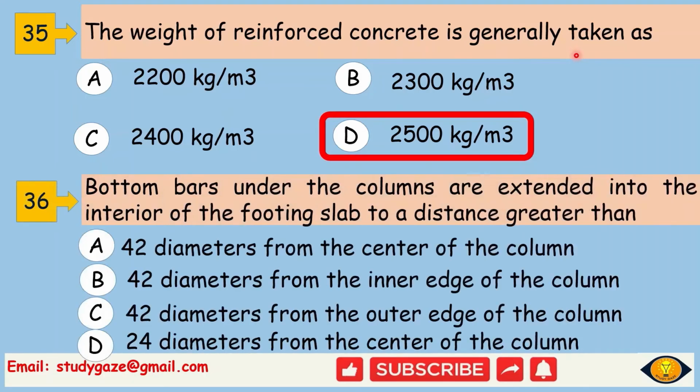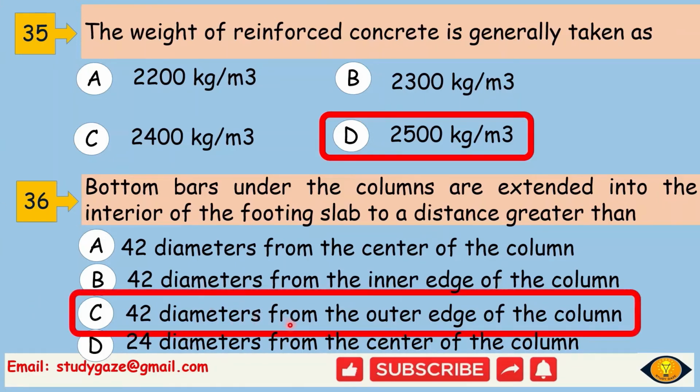Next, bottom bars under the columns are extended into the interior of the footing slab to a distance greater than how much? It should be 42 diameters from the outer edge of the column.